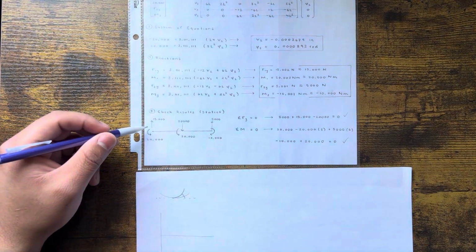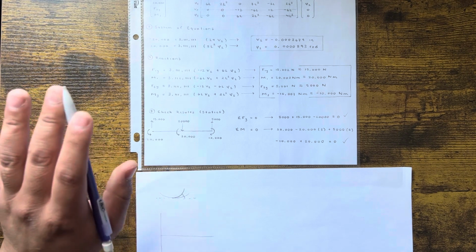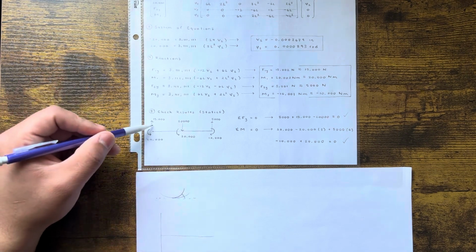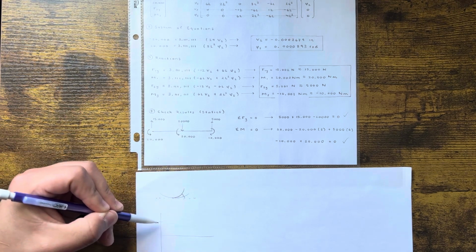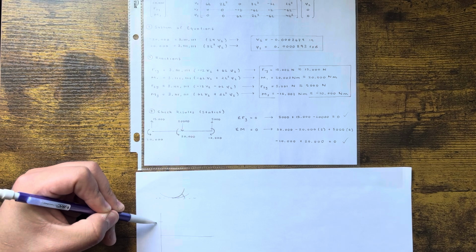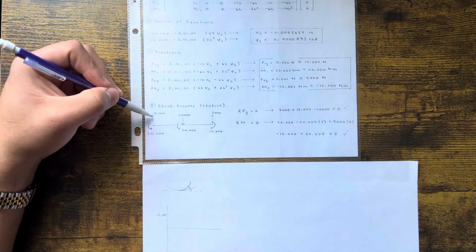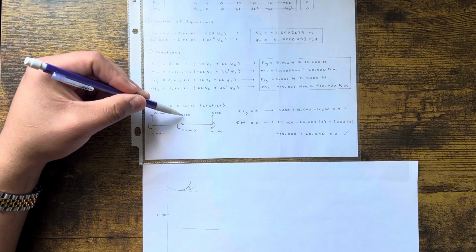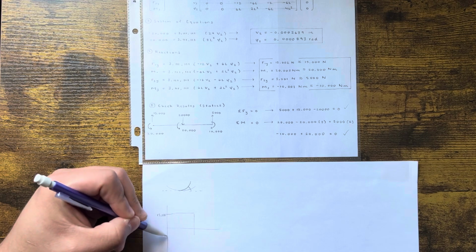So in this case, let's do shear. Bending moment does not affect the shear diagram, okay? So these applied bending moments produce 0 shear. Let's start at the beginning of the beam. You have positive 15,000, so that's going to bring us up 15. And then nothing happens, nothing happens, nothing happens. 20,000 brings you down. So now we're at negative 5,000, right?